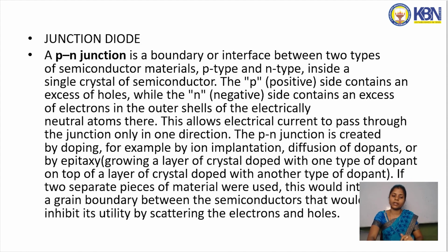So what are the applications of a diode? What real-time applications can we come across when using a diode? Generally, diodes are used in two ways, as a half-wave rectifier and a full-wave rectifier. So what is a half-wave rectifier? Generally, what is a rectifier? A rectifier is used to convert an AC power supply into a DC power supply. We give the diode a power supply, and we get a DC power supply as output by giving an AC input.